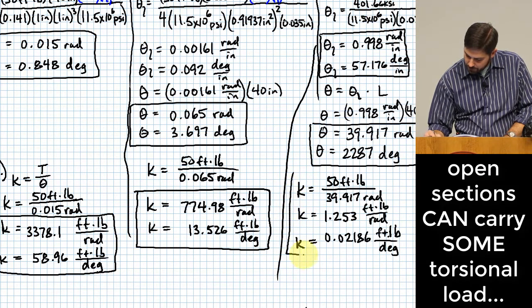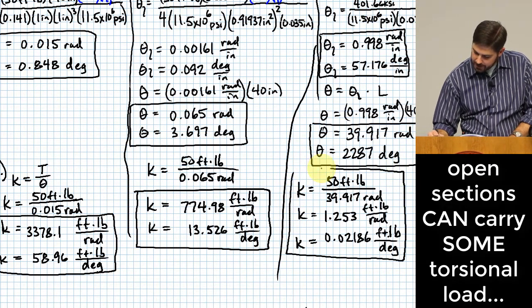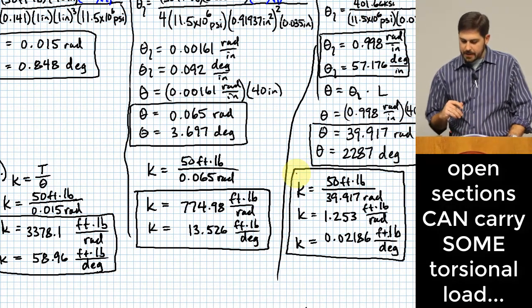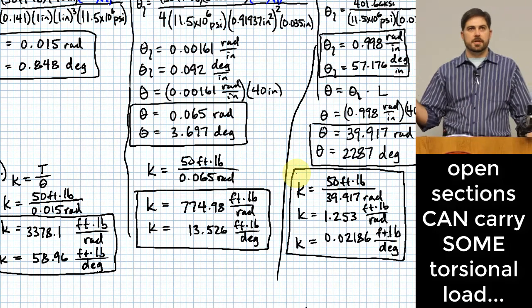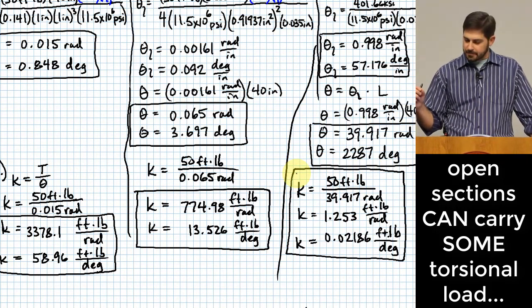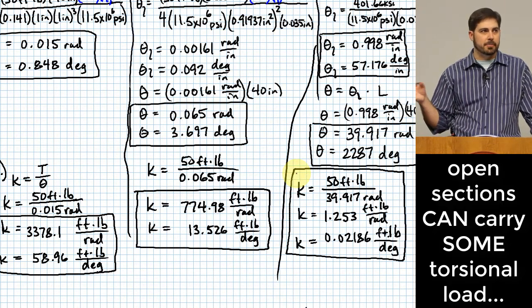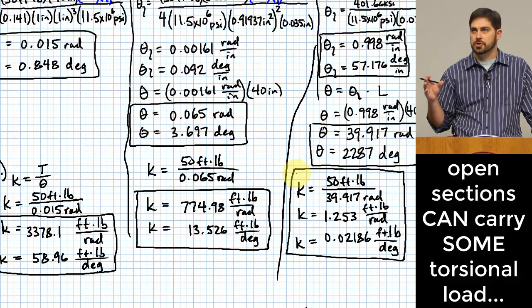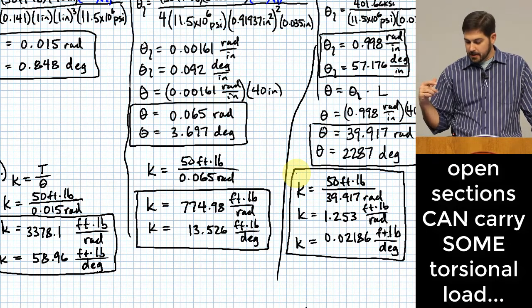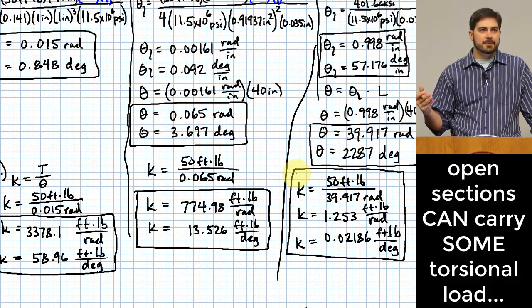All right, my last little comment I'll make here is, even though our open section sucks at torsion, and we want to try to avoid carrying appreciable amounts of load in torsion in open sections, it will carry a little bit, right? So it's sometimes good to know that.